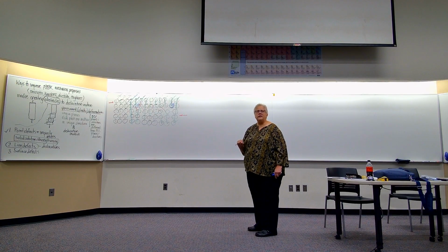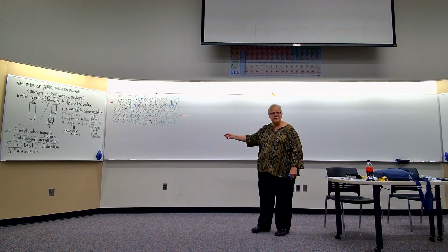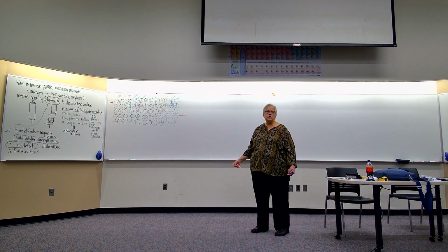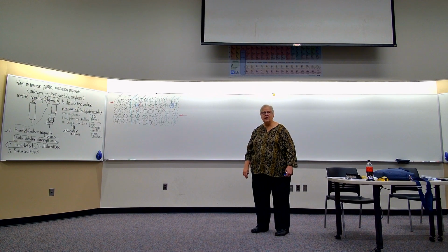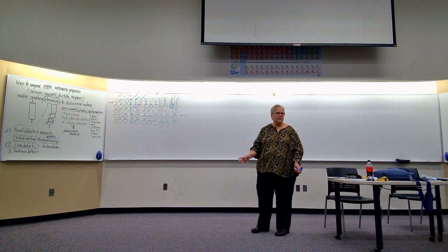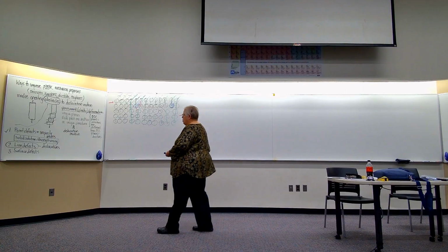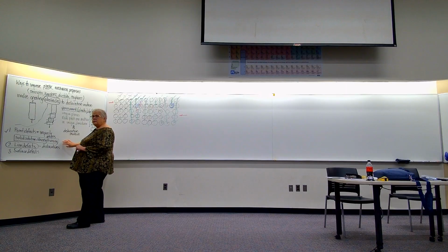So this is how line defects or dislocations are strengthening. If I can get more defects in there, if I can put more dislocations into a metal, I can essentially make the metal stronger. And the number of dislocations goes up as I do permanent deformation. So for adding impurity atoms, I did solid solution strengthening, I did an alloy.